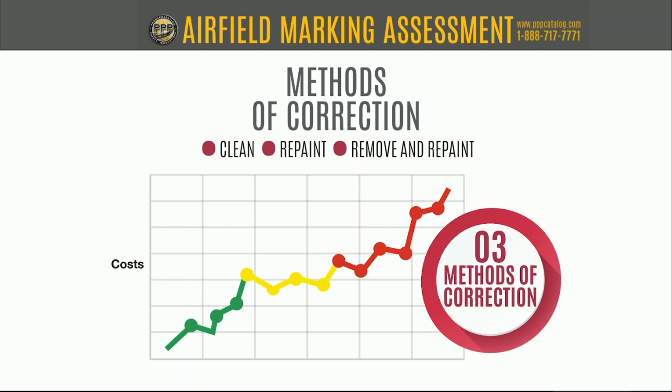Yeah, I think that's a good point. It's something that we should learn in the roadway industry as well. A lot of times you can go out there and clean the lines or clean the signs, and you'll find that you can push that retroreflectivity back up just by, remember, it's light hitting glass and reflecting back. If there's something interfering with that, whether it be algae or anything else, and that light can't get through the glass to begin with, and then come back through the glass, it's going to dramatically decrease the retroreflectivity.